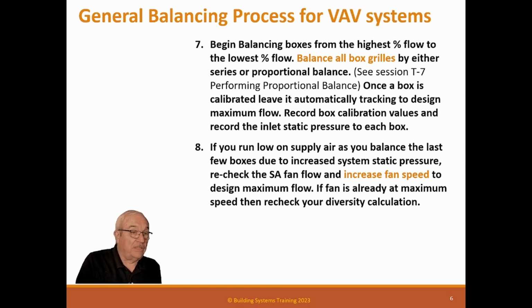If you have a lot of duct leakage, you just may have to have more air out of the fan. Now, if you're operating motors at 1800 RPM or less, you can actually get more air out of that by speeding it up a little bit. I don't recommend you go very far, but you can go to 65 hertz, 68 hertz, something like that, and get a little more air out of the air handler if you need it. You just have to make sure you know how to do that, or you have the VFD guy help you do that.